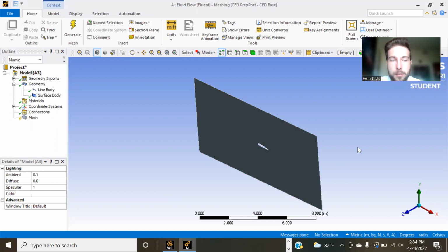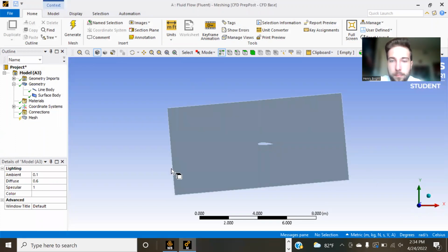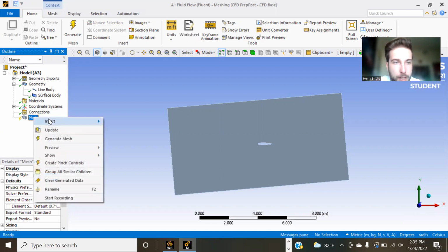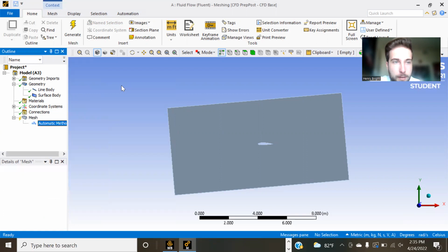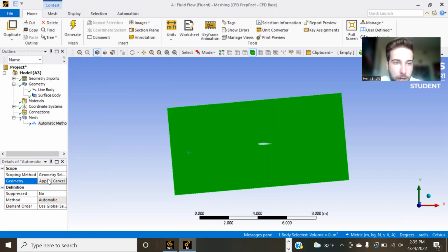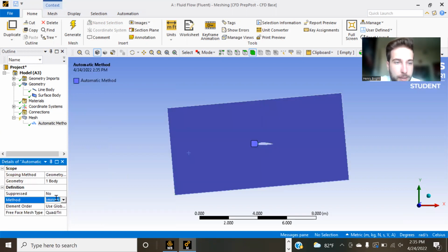Awesome. So we've got our surface. Lovely. Looking at it in 2 dimensions, we've got that. Okay, so we will click on our mesh, and we're going to go ahead and hit insert, and we want to do method. Click on the geometry. And the method that I always do is the all triangles method. You really do what you want, but that's just what I'm familiar with.